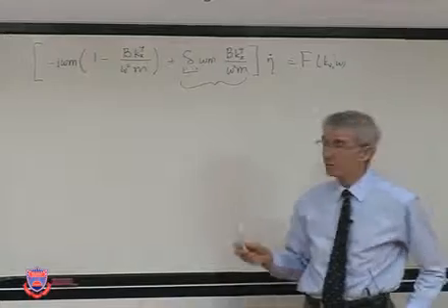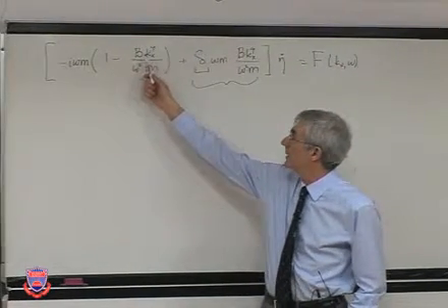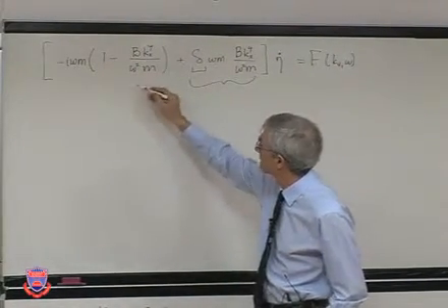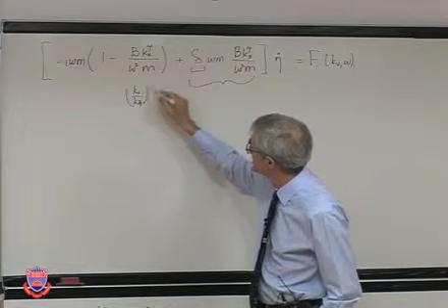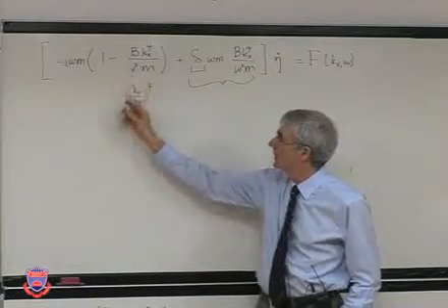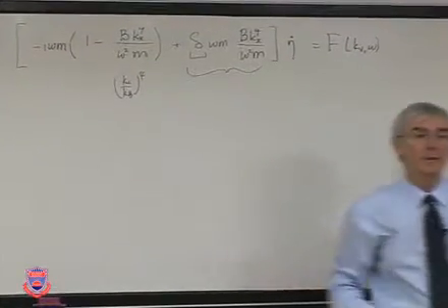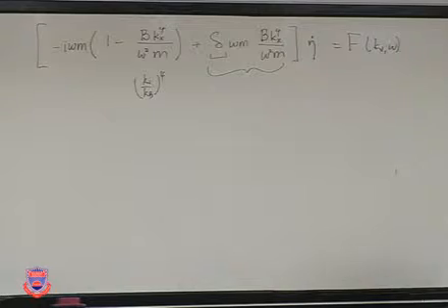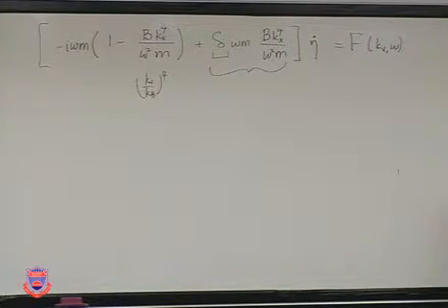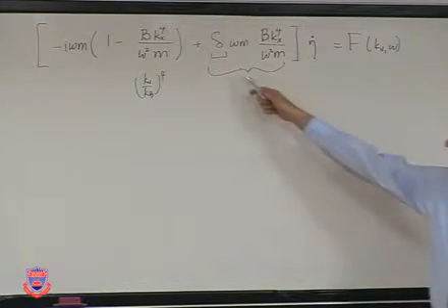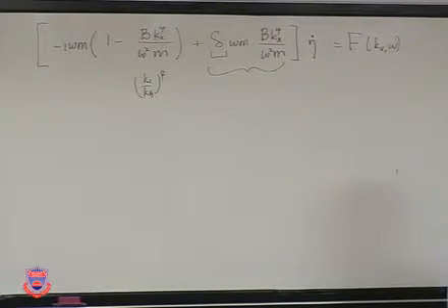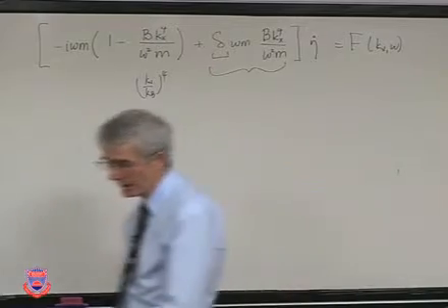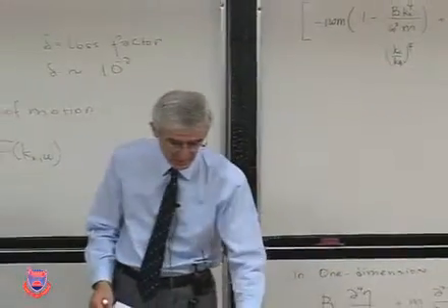Now, what we do see is, by making them equal, you really never get zero. So in this expression, you do not have a zero value for impedance unless the loss factor is completely absent. Okay, this is the way to express damping in plates or beams, for that matter.